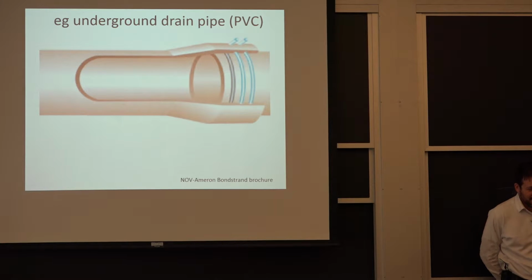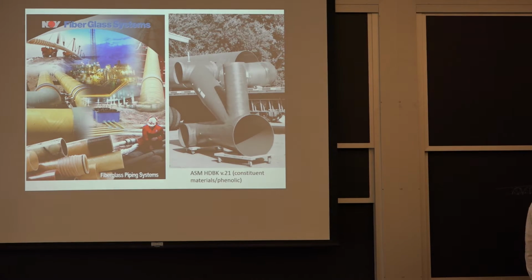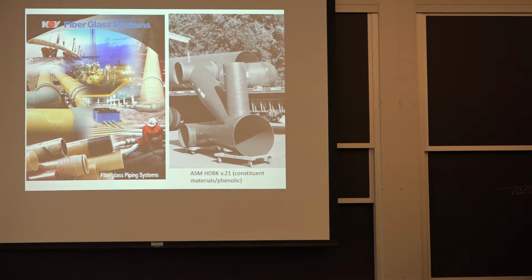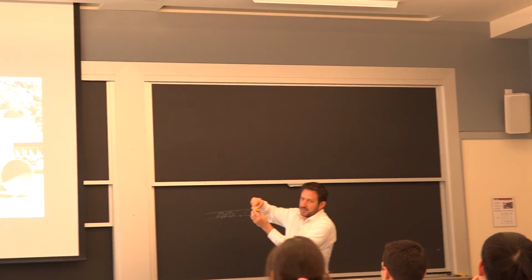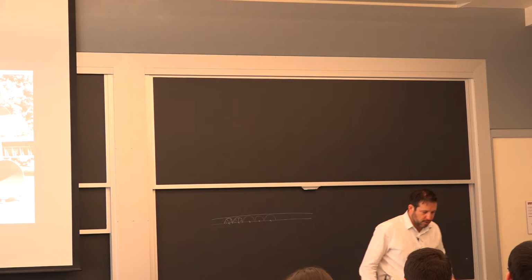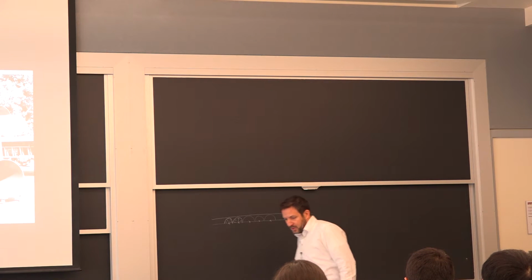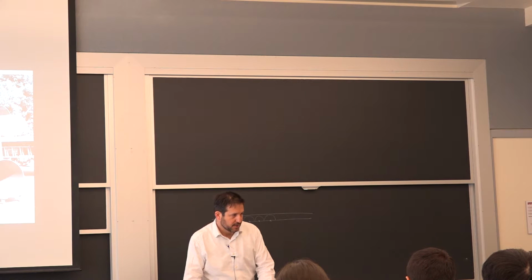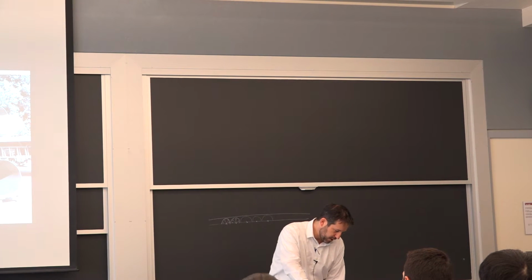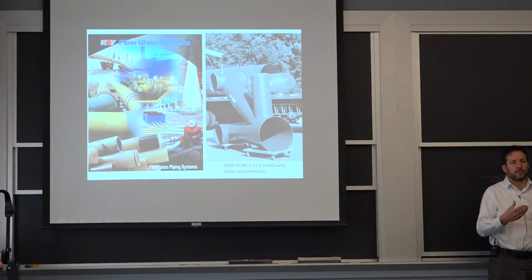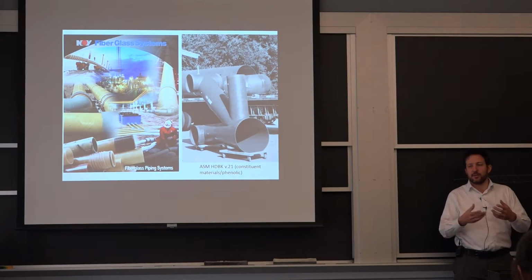Practical engineering. Okay, composite pipes. And this is going to really help us tie into this whole material selection module. I brought one cross section of it. It's not all that clear, but on the upper side, so the side towards the center, you'll see that there's a clear layer. And there's one issue with composites, even though the polymer, is moisture penetration. When you get that polyester resin or whatever resin you're using to be fully absorbed with moisture, you're losing the good bond between the composite and the resin.